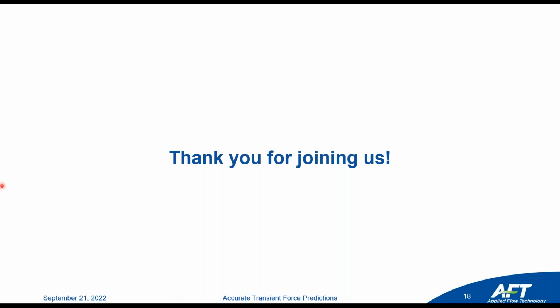I see another question here: can the software predict the force flows on a horizontal split case pump in which the suction inlet comes in vertical and exits horizontal? I would say for more complicated arrangements like that, we can't just directly say, this is the force. But with that point force that Trey had mentioned, we can tell you the forces acting at different locations in the system. You would have to take those and make some conclusions off of them. So we can give you good information about the hydraulic loading that pump might be seeing, but there is some work on your end that you'd have to put in to interpret those.